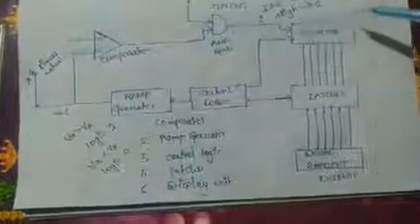Next, the output of the AND gate is connected to the binary counter. It means the counter counts the clock pulses and stores them. Here, for the storing purpose, we are connecting latches in series with the counter. The output from the counter is given to the latches, then to the display unit. The output from this total completed circuit is shown in the display unit.